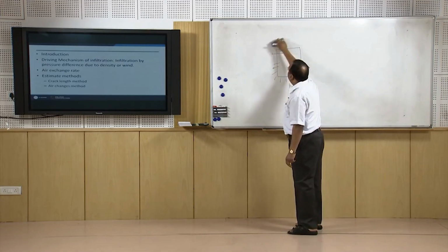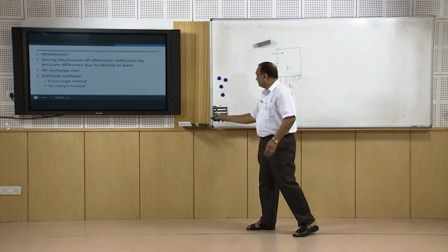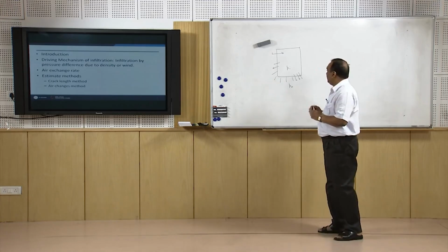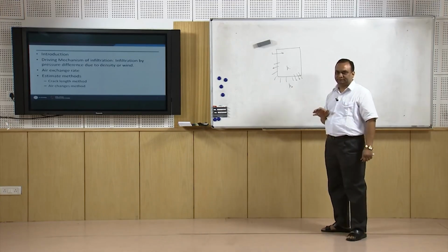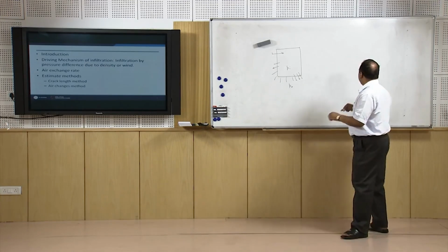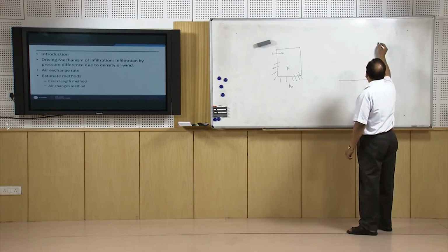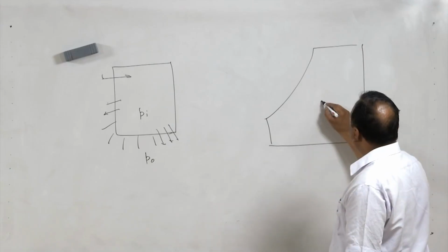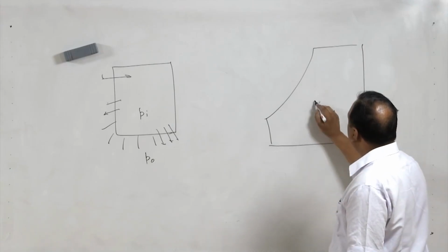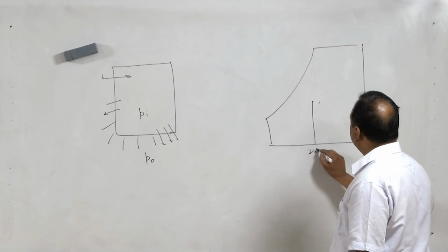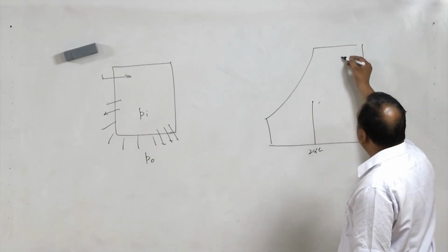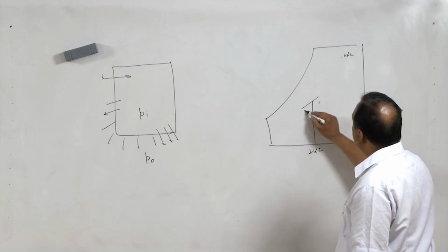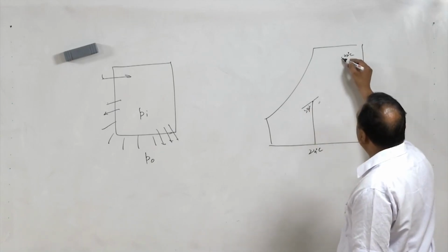And how we can prevent the infiltration of this air into the building, because infiltration brings load on the cooling coil also. For example, inside the room, suppose the room temperature is maintained at, let us say, 24 degrees centigrade, and outside air is 42 degrees centigrade. This is 24, 50%, and this has some humidity, let us say 60%.